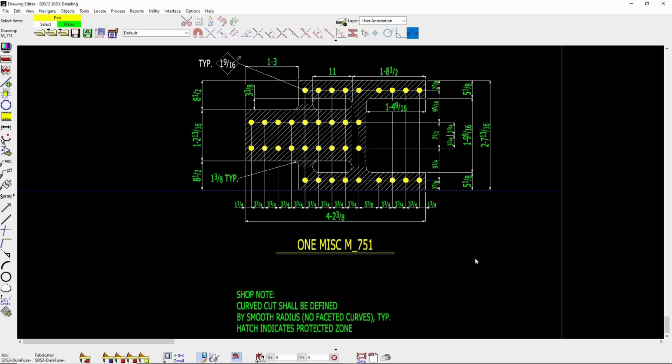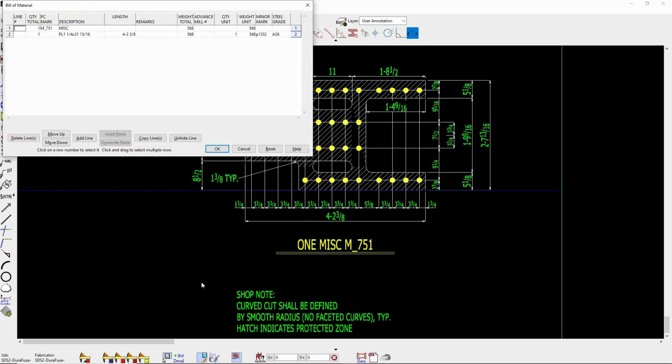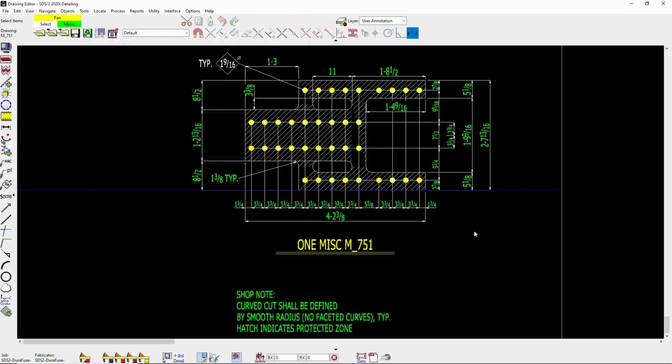So the typical material grade is A572, grade 50. And the plates can be painted, but the faying surfaces need to have a Class A faying surface. So if you do paint it, just check to make sure the paint is rated. Okay. Another one popped through. Can we paint the framing at the connection? I think you might have just answered that.